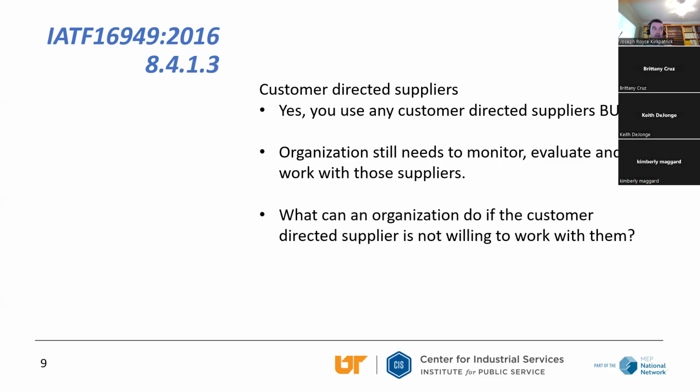Customer-directed suppliers. IATF says, yes, we need to use customer-directed suppliers. If the customer says we've got to use Nippon Steel for the steel that we purchase, well, we need to use Nippon Steel if that's what they demand. But the only thing that absolves us from is the selection process. We don't have to select them. But we still need to monitor them, evaluate them, work with them, hold their hand.